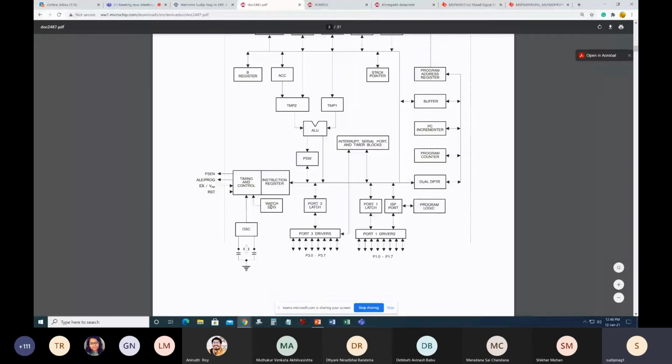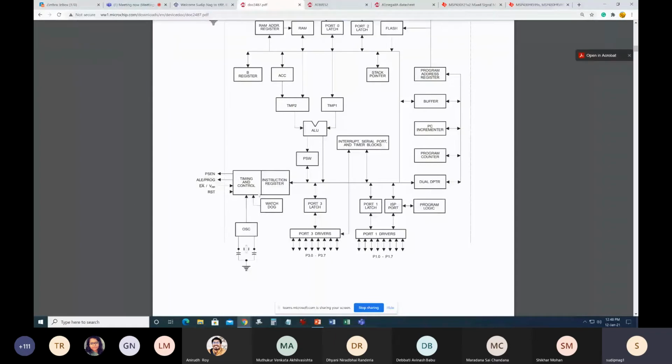It's like the barking of a dog, giving a signal to the timing and control, and as a result it tries to reset everything. So it's an internal reset after every few milliseconds. Ideally we don't want that all the time, but sometimes it is good for safety. If the program hangs, it will automatically come out of the hanging state and start from scratch. But you can disable the Watchdog Timer, and enable it if necessary.